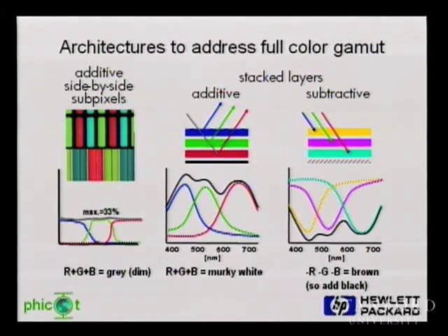So that means that if we want to have green, we're really only having 1/3 of the surface participating in that. But it's really not a problem because we've got a backlight, so we just crank it up so enough light comes out of it that we still have a bright image. Now the problem is that if you do that with a reflective display, the only light you have to come back to you is the light that reflects on it. And then modulo, there's the optical losses in the medium itself. So what you get reflected back to you is really going to be a lot less than even 1/3 of the light that's incident.